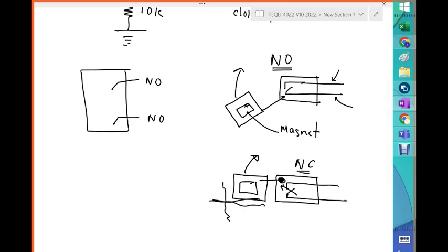If you put this level switch in this position, where the magnet can pivot up, in most cases it's going to be normally closed. The other one, if this can pivot this way, the only way that this can go is up, because that's how you put them within the vessel. So normally open, normally closed. These two switches, switch 1 and switch 2, are normally open switches.